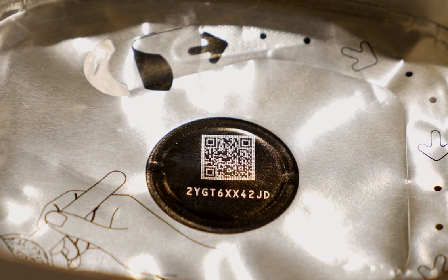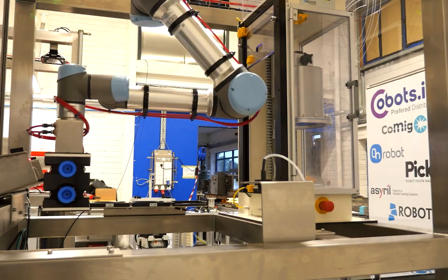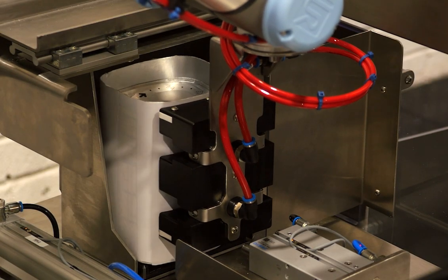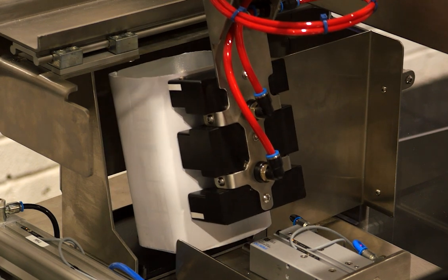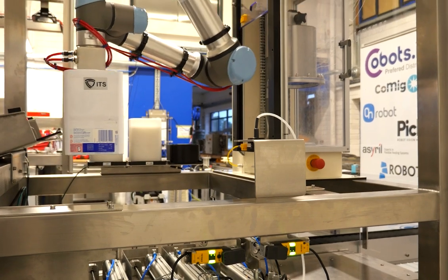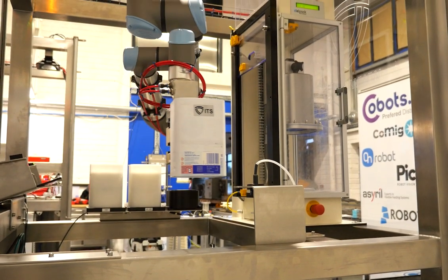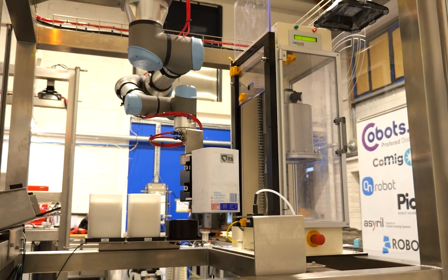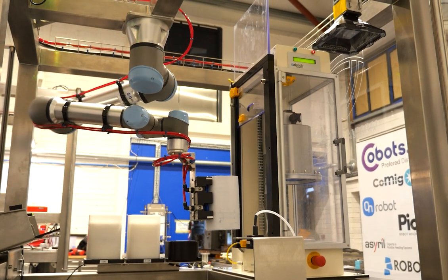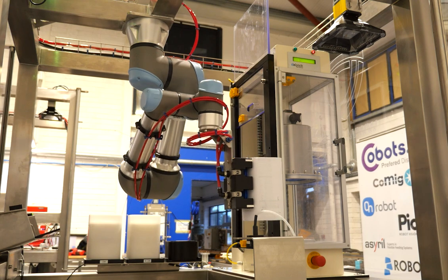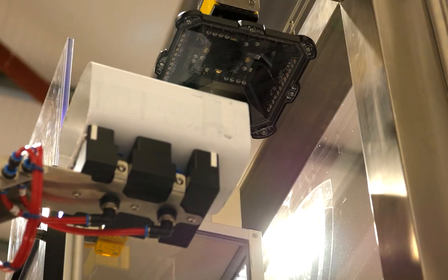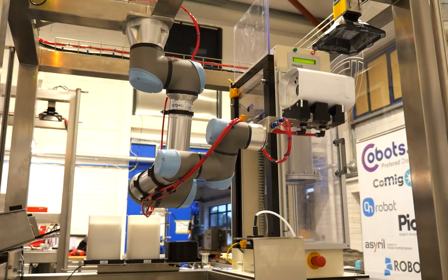And then, based on those, if they're a pass, the robot will take the part to a seal integrity tester, where the seal will be checked, and if that is a pass, the part is taken to the outfeed and passed out to the operator. So you can see the robot presenting to the scanner to read the barcode. It'll then also present the part to the same scanner, which will read the data matrix on the top of the foil seal. It then moves over to the pressure test,